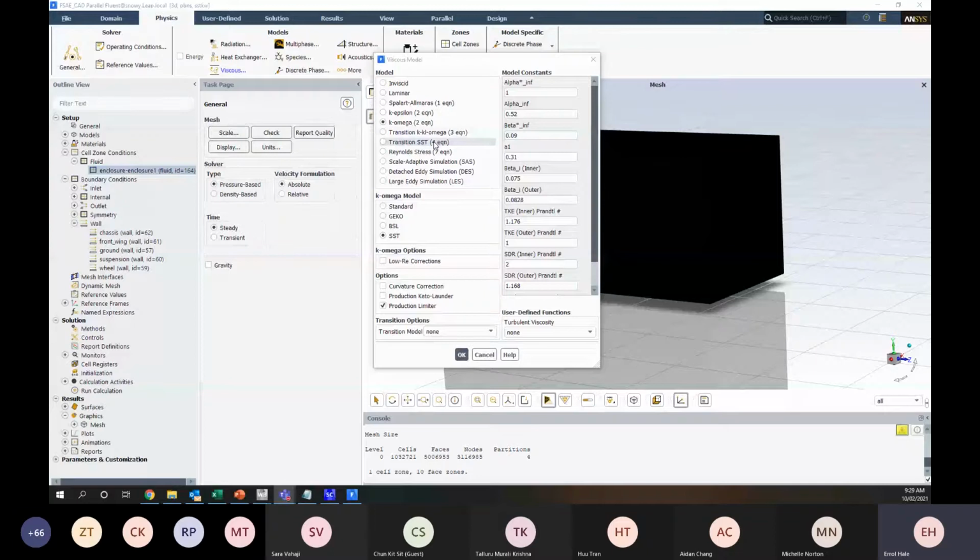And as we'll go through later, capturing what's happening in the boundary layer is really difficult, but it's really important because that's going to tell you things like where your flow is separating, especially for cases like wings and wheels, where your flow separates. The exact point your flow separates has a really great effect on your actual aerodynamic performance, so your lift and your drag values.